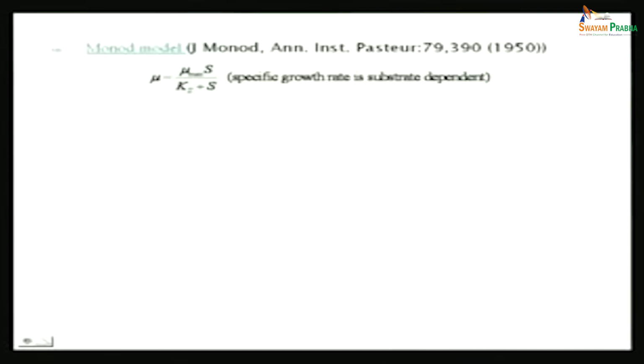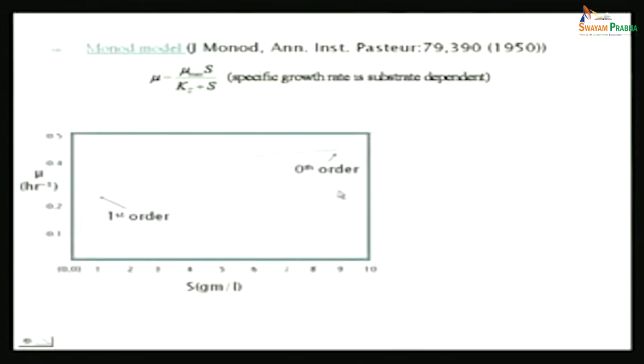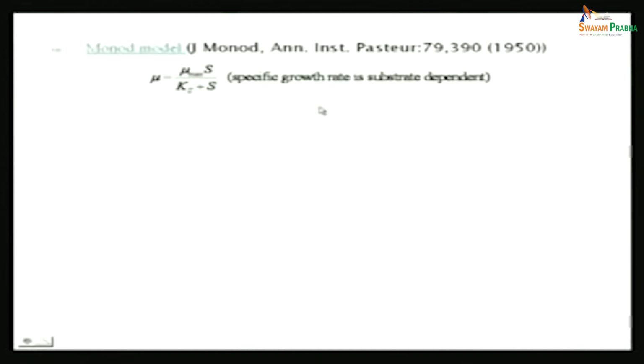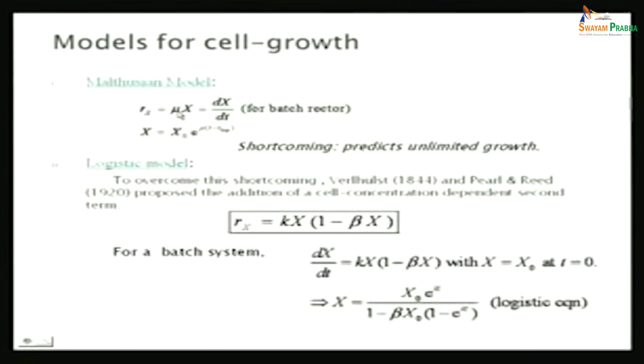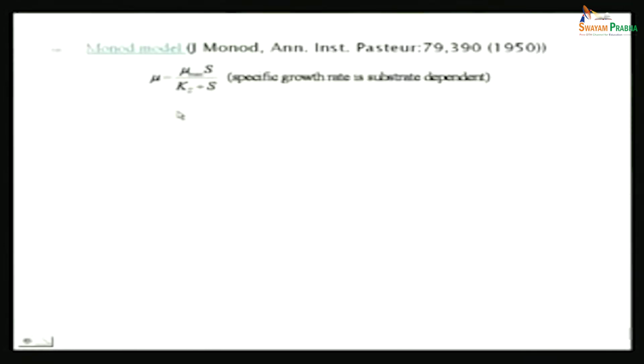So, what the Monod model says is that Rx is mu times x, and you don't need to include another part, but let this mu be dependent on the substrate. If there is a depletion of the substrate, the rate constant for growth decreases. Interestingly, what have they done with the rate constant? They have put Michaelis-Menten kinetics there.